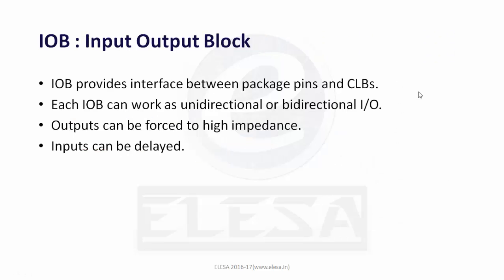Now the next thing is the input output block. The input output block provides the interface between the package pins and the CLBs. Each input output block can work as unidirectional or bidirectional input output. The outputs can be forced to high impedance. Inputs can be delayed. These are the features of the input output block. So we will understand this by its block diagram.